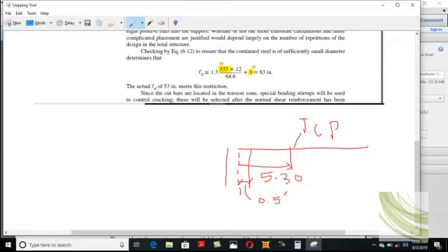They say in that sentence that this bar should be continued for a distance of 3 inch past the end of the beam. This is the end of the beam. Okay, here they consider this is the end of the beam. Although this is the end, where the beam ends, the diagram starts from this point.